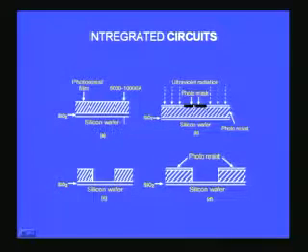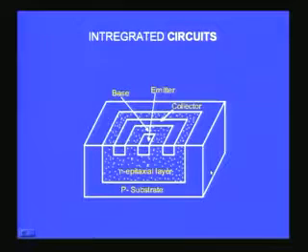Whereas in this place you have put a photo mask, and therefore it will cover the region. So then you can actually etch. When you put an etchant here, you would find the etching will happen only in the place where there is no mask, and in all other places there won't be any etching. So thereby you can form different patterns, very sharp fine details on the silicon chip, and therefore you can have different types of devices developed over this. Let me not go too much deep into that, but I just want to show you another picture here